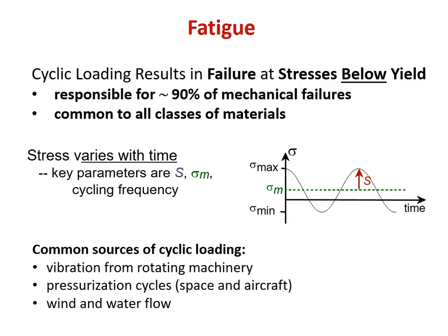This happens across all classes of materials. Nothing is immune. Polymers, ceramics, metals, they all have it. We'll see in the case of metals, there's again a difference in face and body-centered cubic, with the face-centered cubic materials not having what we call a fatigue limit, but they're still subject to fatigue.